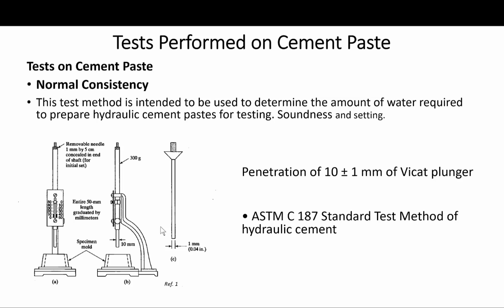This test is a measure of the plasticity of cement paste, although it does not correlate particularly with the quality of the cement though. So just keep that in mind. It is very sensitive to the conditions under which it's carried out, especially temperature and the way the cement is compacted into the mold. So again, comparing these results though, we're talking about here consistency, and the personnel doing the test has to be doing the tests over a certain period of time or for a certain application to ensure consistency.